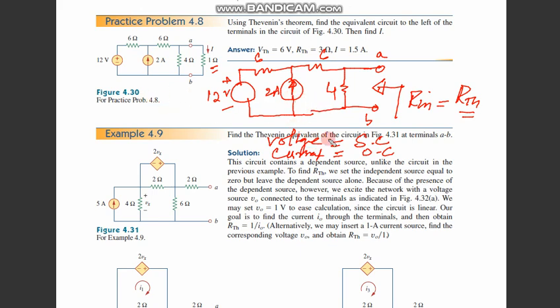By applying these two rules, our circuit becomes, from the A terminal, this 4 ohm resistance, this is my B terminal, then this is 6 ohms. I ignore the 2 ampere current branch, which is open circuited, then I have the 6 ohm resistance, and the source becomes short circuited over here.